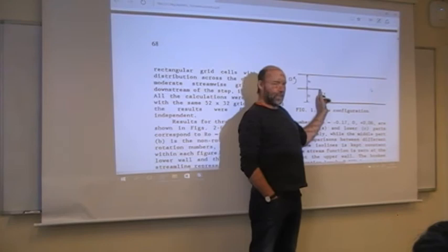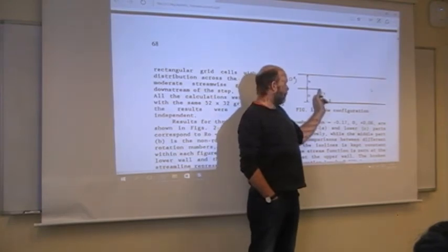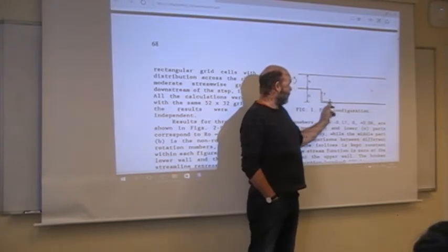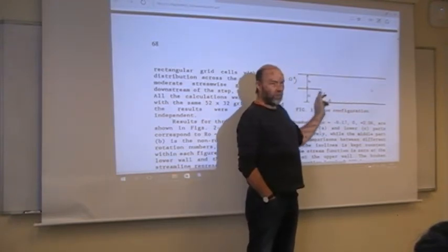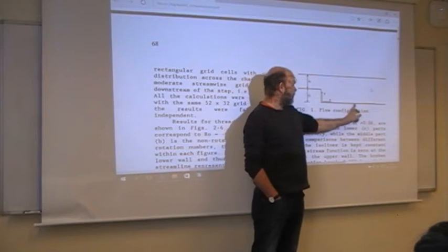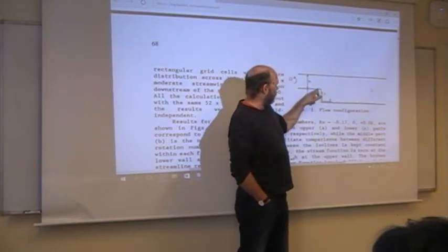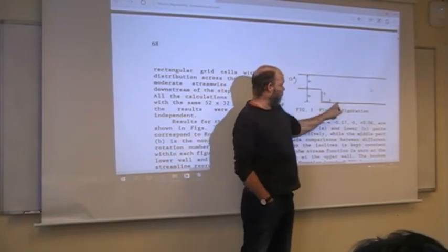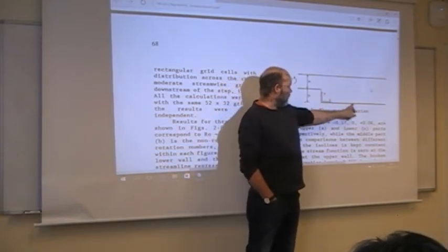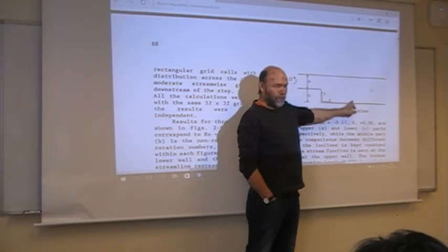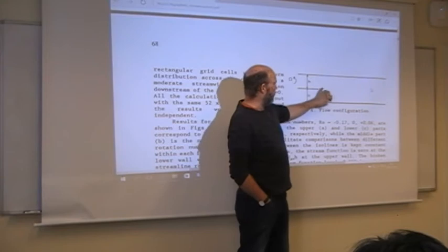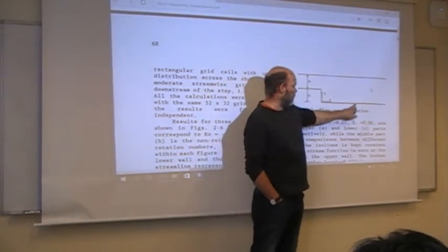With the backward facing step, what's interesting is typically the main result here. How big is this vortex going to be? So we are seeking the reattachment point here, where you have one streamline separating this primary vortex, and according to theory, it should be 6, 7 step heights downstream.